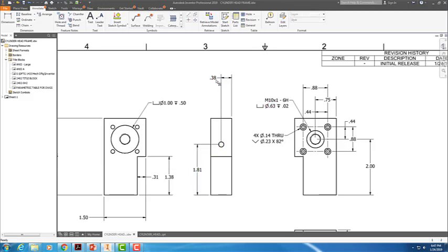Okay, I'm going to drag this down a little bit more. Okay, then I need a hole and thread callout. That one gave me the depth. Now be careful. Sometimes you want to go and look at the part, make sure. If they say they're all going through all, make sure that they are.